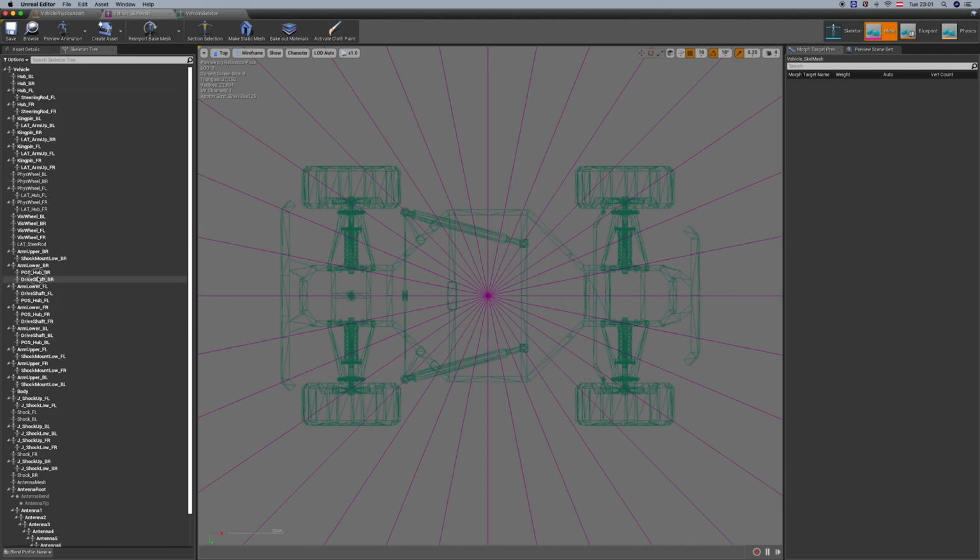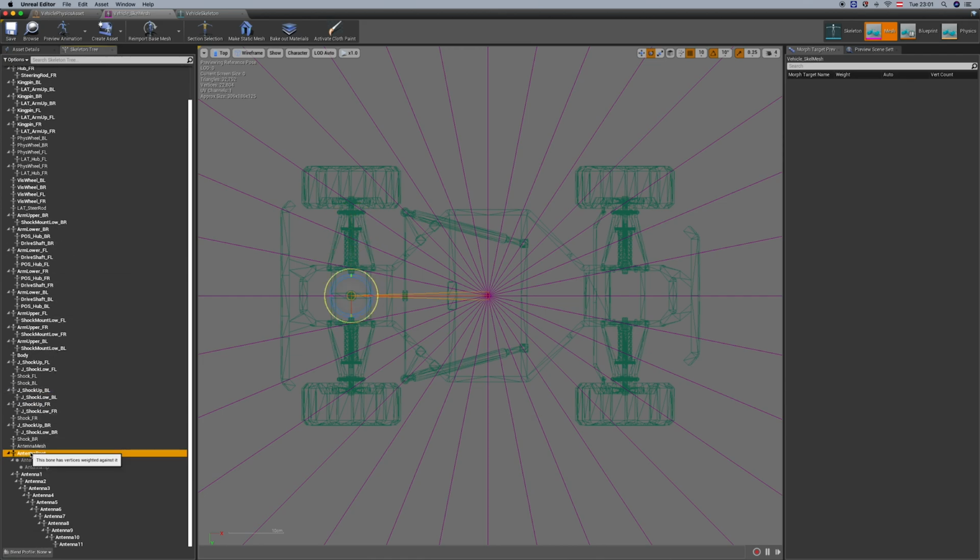So for example, here we have the skeleton, and what we see here is one bone that starts from the center of mass of that vehicle and ends here at the center of the right front wheel. And what I am looking for is this point here, so I need to just keep going down. I know it is, yeah, the antenna root. So here we have actually an antenna in this car, and this is basically the antenna root. So we need to copy this selected point name. Just keep it in mind because we will use it later. And this is basically the antenna root.